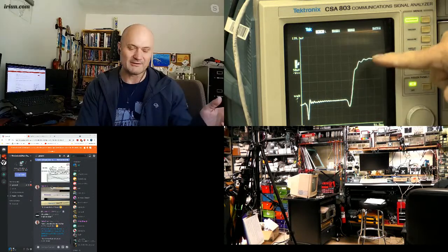As you go left to right across the TDR screen, you're also seeing a signal bouncing back, traveling right to left back up the wire, in the opposite direction. You have to keep that in your head and mesh it with a causal, time-based waveform on the screen. But you can use any oscilloscope as a TDR if you set it up right. You just need a pulse source in the frequency range you're looking at.